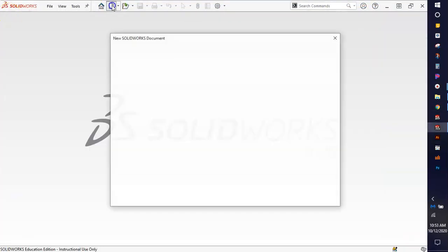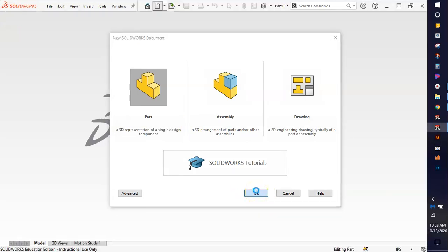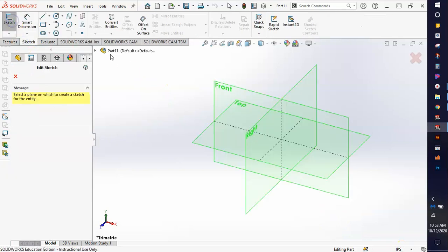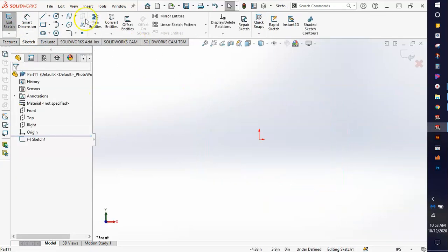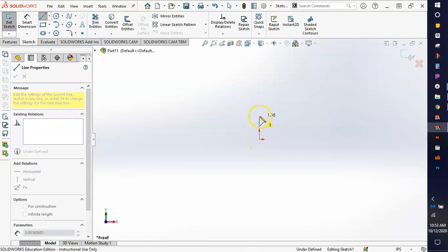And in SolidWorks, let's make a new part file. So I'm going to be sketching right on the front plane, and I need to make sure that my units are in IPS. My computer defaults to that, so I am good to go. And I'm going to sketch right here on the front, and I'm going to try to draw out the entire picture. So just get your line tool, start right on the origin in that corner, and just kind of work your way up. And it goes on an angle, it goes in, up again, it's a little cutout here,